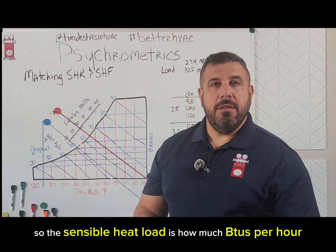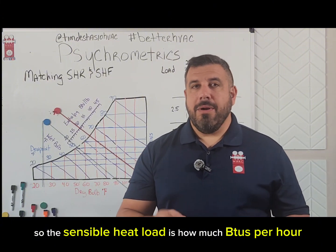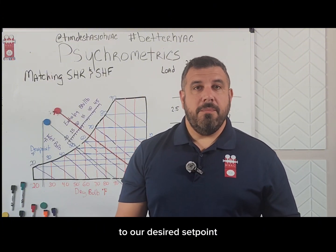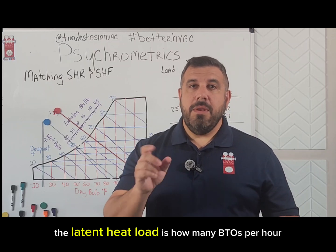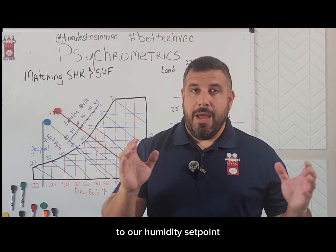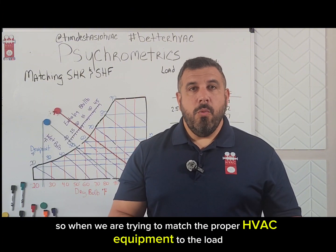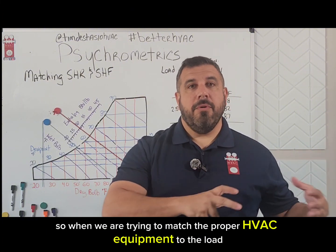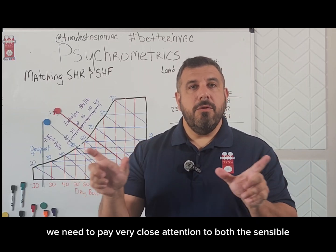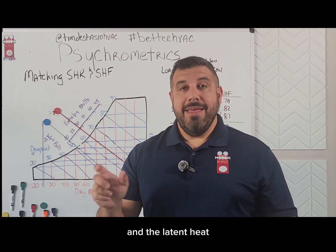Total heat is broken up into two parts. The sensible heat load is how many BTUs per hour it's going to take to control the temperature in the building to our desired set point. The latent heat load is how many BTUs per hour it's going to take to control the humidity levels to our humidity set point. So when we are trying to match the proper HVAC equipment to the load, we need to pay very close attention to both the sensible and the latent heat.